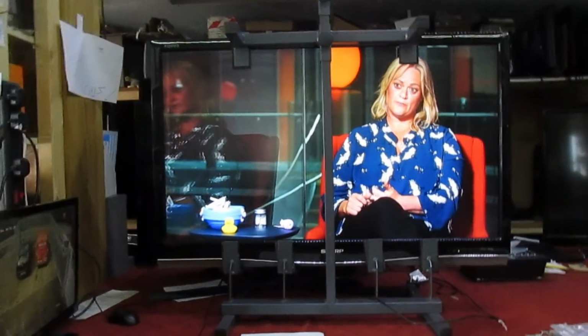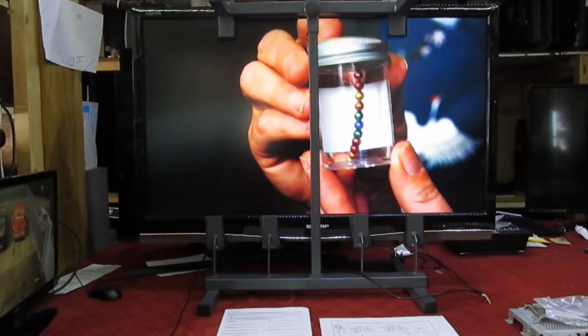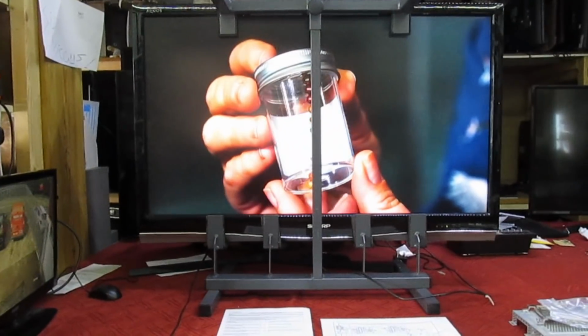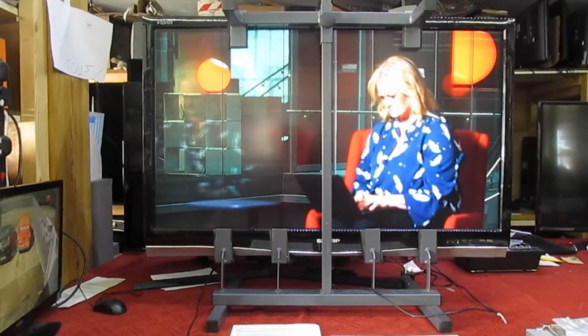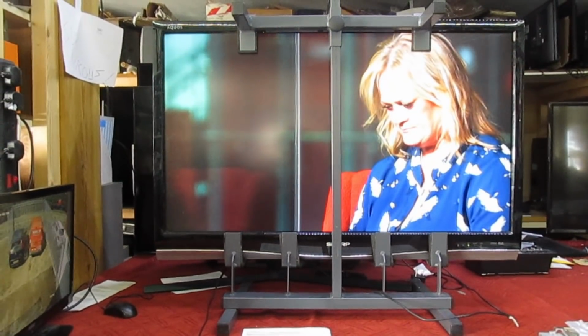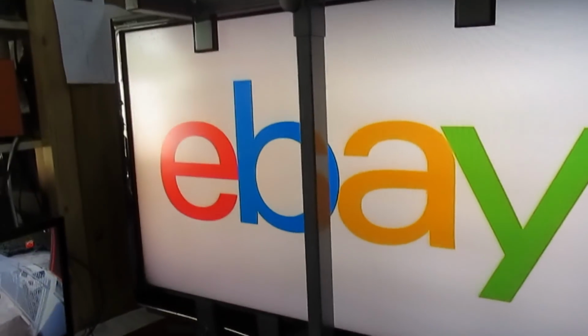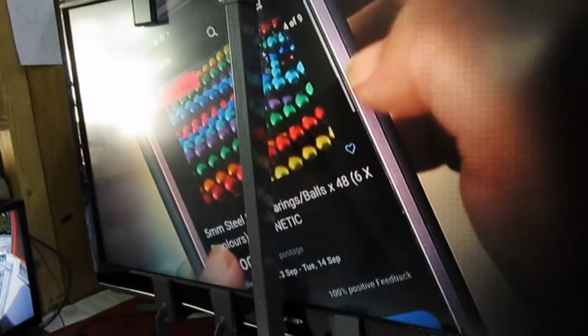Right, so there we go, guys and girls. A relatively simple fault on a 10-year-old TV, but it's not all about the TV. This video was to demonstrate the importance of checking the supply lines before you get too deep into a fault. Don't overcomplicate things. The basic rule of electronics is, before you do anything else, always check that the supply lines are bang on. And if you remember, in this case, the 1.3 volt rail was only 300 millivolts down. So it's not about the TV, it's to highlight this particular problem, that you should always check voltages first.